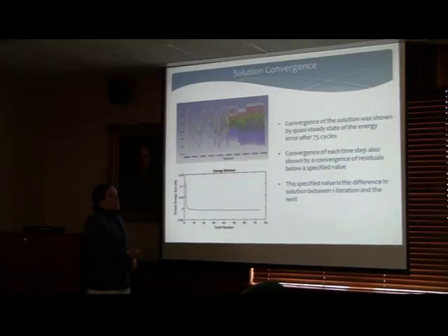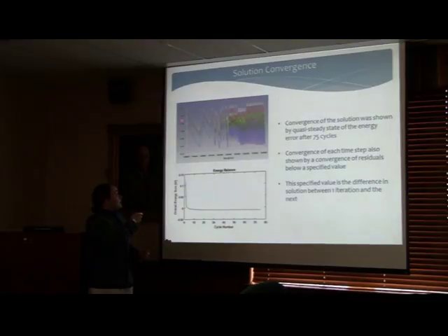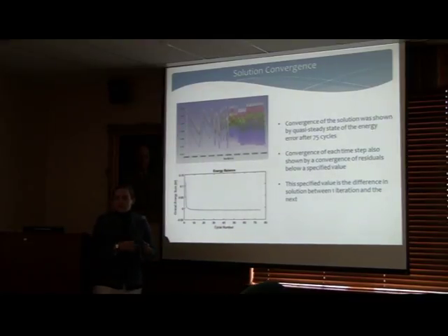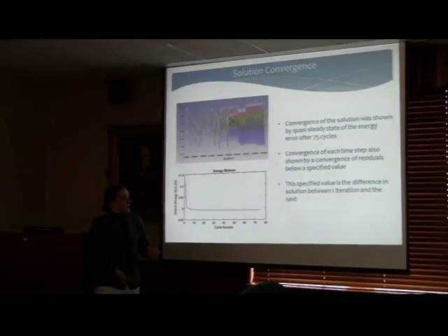All this shows you is that one iteration is the solution of all your continuity and energy equations, and then the next one differs by no more than 1e-4. So it's showing you that over time, the differences between iterations are getting even smaller. These are the 4 different things that it's solving for, and as it goes, it shows that it's converged between time steps.